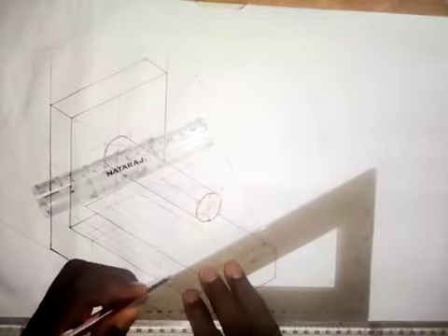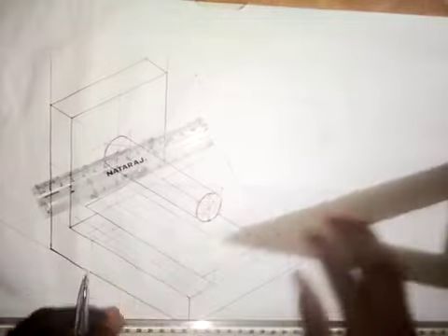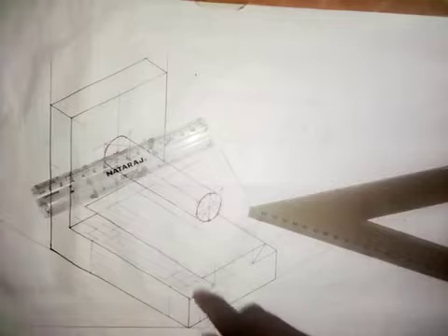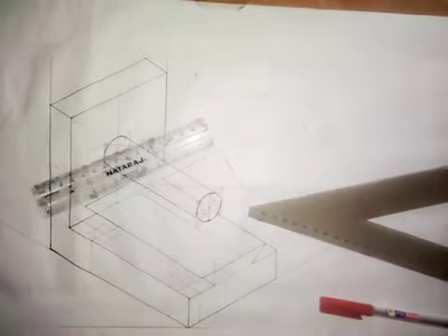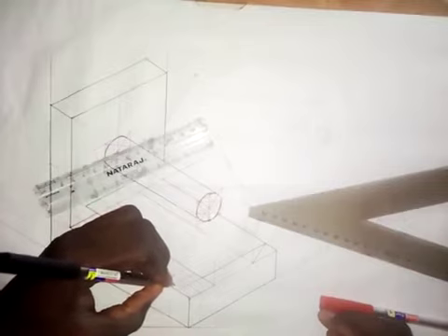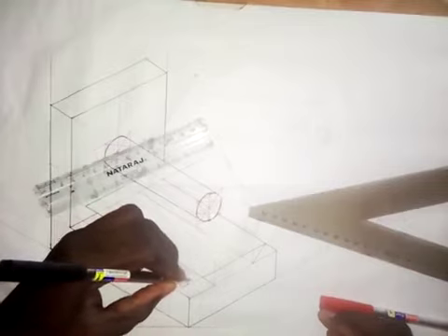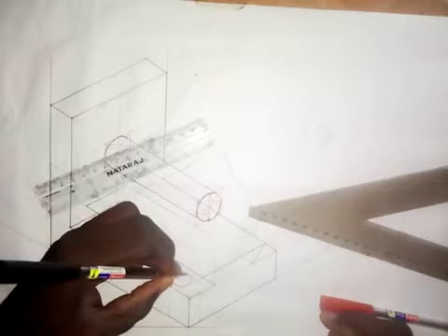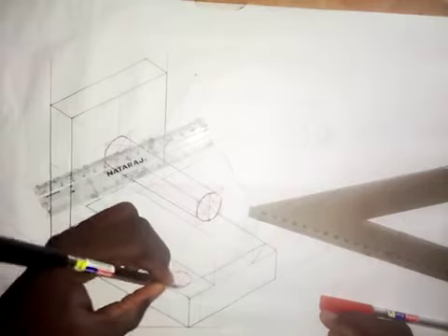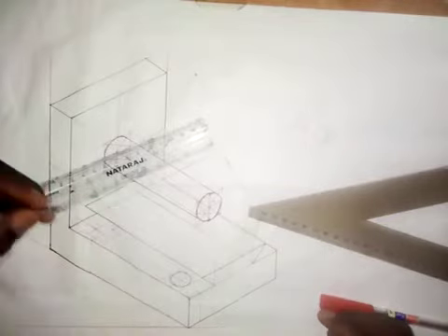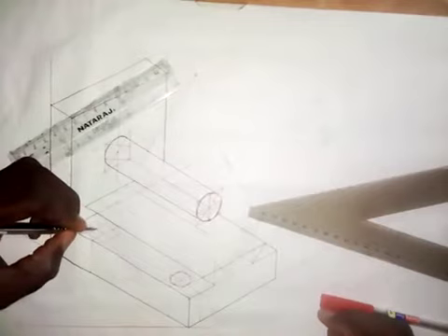Okay, so we are forming the isometric square because we want to produce an isometric circle. So for this, I'm going to join this together. So I'll just join this point together. I'm going to use my hand to form the isometric circle because this is very small. So an isometric circle is an ellipse. So this is how I use my hand to form an isometric circle if the square is small, as we have here. So I will also do the same thing on this side.